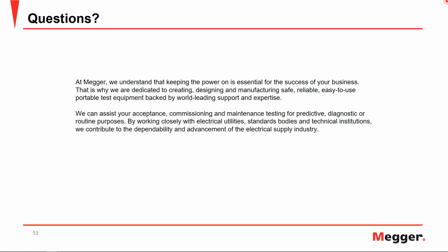If you expand that frequency range, you also have the ability to estimate the moisture present in the cellulose. So there are different variations of power factor testing. And if you are talking in general about insulation assessment, there are other tests available like DC insulation, PD, and high pot. On cables, you do VLF testing. There are a number of other tests that can be used for insulation assessment.